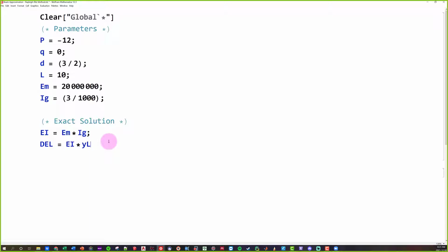So for the left-hand side, I'm going to call it YL, or basically my displacement function for the left. And this is the fourth derivative, so I'm going to go 1, 2, 3, 4 derivatives, and we know it's a function of x1. Now we know that technically this term right here in our differential equation is equal to our distributed load Q.